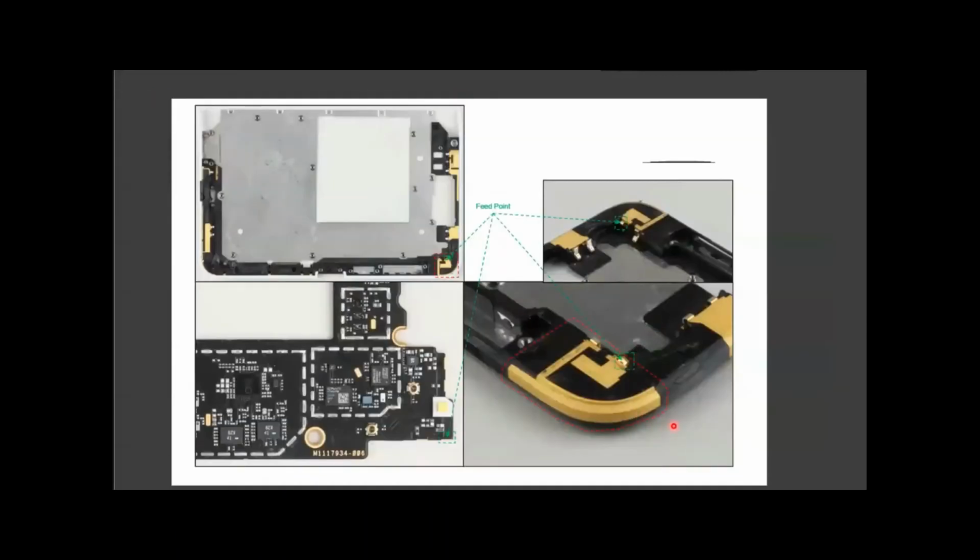Let's move on. And then this antenna, which is at the top of the device on the corner, does a few things. It does MIMO, so it does the 1700 megahertz to the 2.7 gig. It also does Wi-Fi. So this actually incorporates a concept called antenna sharing. We multiplex different protocols into the same antenna, so in some cases we're able to share antennas that do very different jobs.